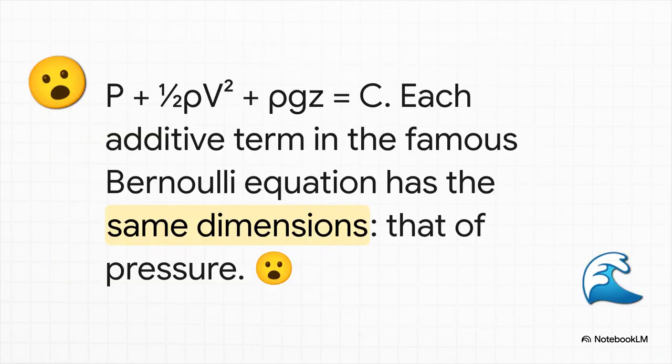Take a look at this famous beast, the Bernoulli equation. It describes how fluids move. Now, it looks like a mess, but you've got three main parts here. One for the static pressure, one for the pressure from the fluid's speed, and one for the pressure from its height. And here's the cool part. When you break them all down, every single one of those terms has the exact same dimensions, the dimensions of pressure. They're all speaking the same language.